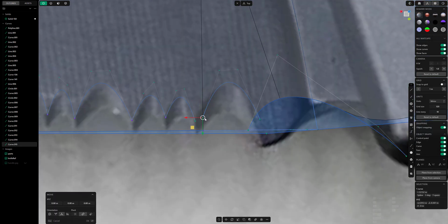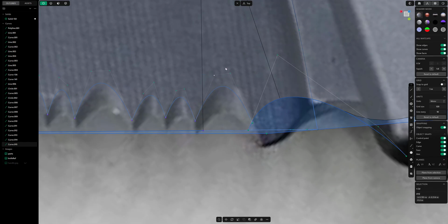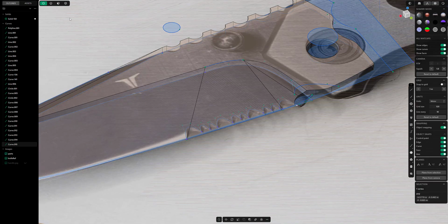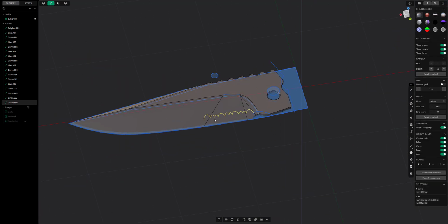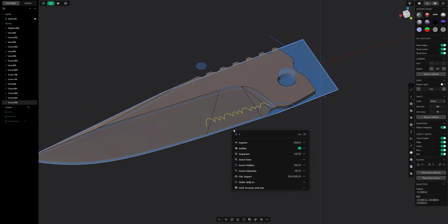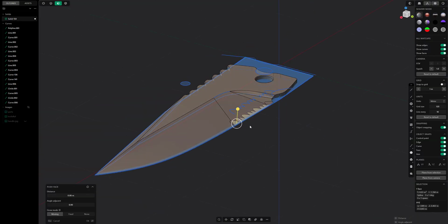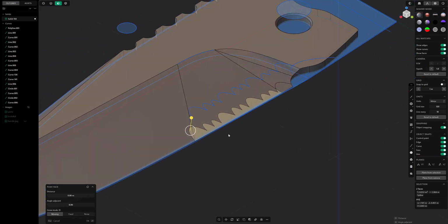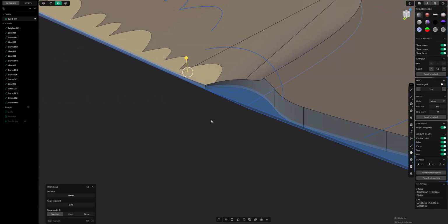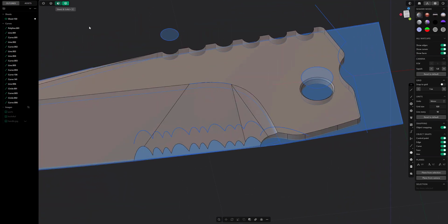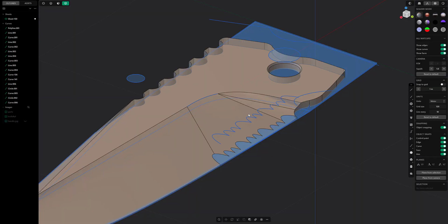This last one's a little bit interesting because it goes all the way through. So I just drag it all the way to the edge. I can take all of these edges and join them together so I get one curve. And then we can either imprint them or we can cut them. I think actually here we could try this. I tried pushing it through, but it doesn't want to work. So I could just take those, imprint, and then delete. Cutting would have worked fine too. Probably would have been better.